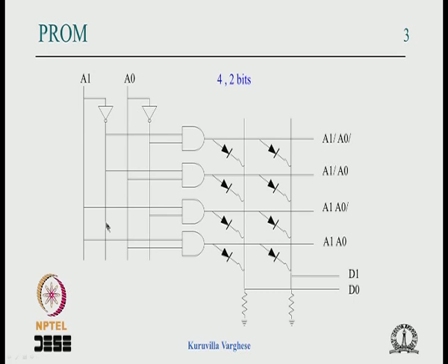Then we can reduce the number using some statistics. You study Boolean functions of different variables, 5 variables, 6 variables, from practical cases, and say in 80 or 90% of cases for a 5 input scenario you don't require more than say 14 minterms or something like that. Then you can use only 14 AND gates.